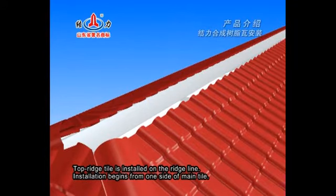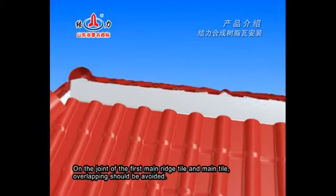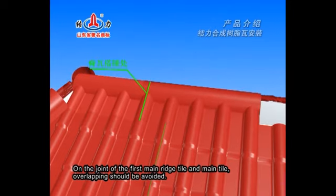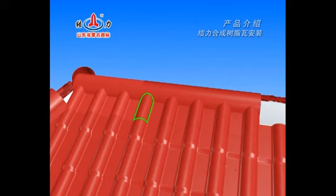Top ridge tile. Top ridge tile is installed on the ridge line. Installation begins from one side of the main tile. On the joint of the first main ridge tile and main tile, overlapping should be avoided. Overlap one wave unit between two top ridge tiles.